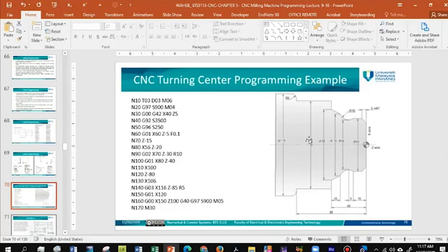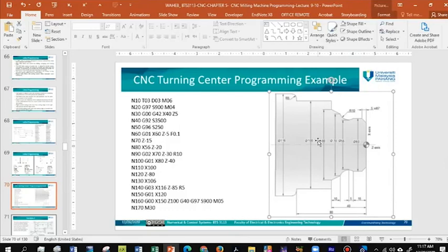Also previously in chapter 2, when we talked about incremental and absolute coordinates, we highlighted how we can find them either for radial or for diameter. For diameter, we said we need to multiply by 2. For radial, we just talk about the half part, or the top part, of our workpiece here. So this is a simple program used to create this shape from the original shape, which is a fully cylindrical part. We need to define different coordinates with different types of codes, G00, G92, G96, G01.